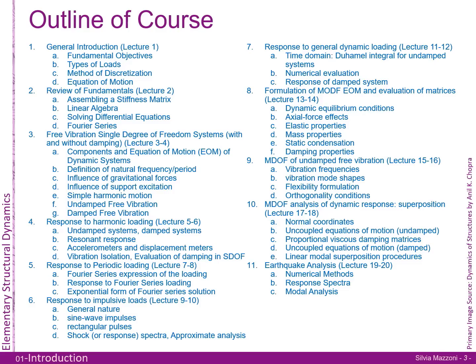We're going to look at the response to general dynamic loading through the time domain, so the Duhamel integral. We're going to learn and get familiar, and we're going to use the Duhamel integral for an undamped system. We're going to look at numerical evaluation and numerical methods, and the response of a damped system. From there, we've developed all the basic tools that we need, but we're still limiting ourselves to a single degree of freedom system. So then we're going to move on to a multiple degree of freedom system, MDOF, equation of motion, and the evaluation using matrices.